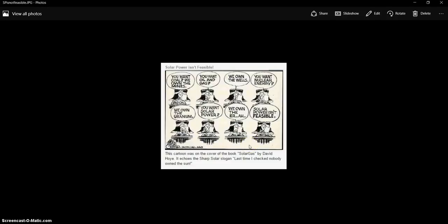Hello, today I'm going to talk a little bit about solar systems, and like I promised in the blog, let me start off by showing you how you calculate the capacity for a system. There are two items you have to calculate capacities for: the solar panels themselves, to determine how much you want to generate, and the capacity of the battery system you want for backup and any surge, and for bad days. And bad days are when it's cloudy or if there is snow and it covers up your panels.